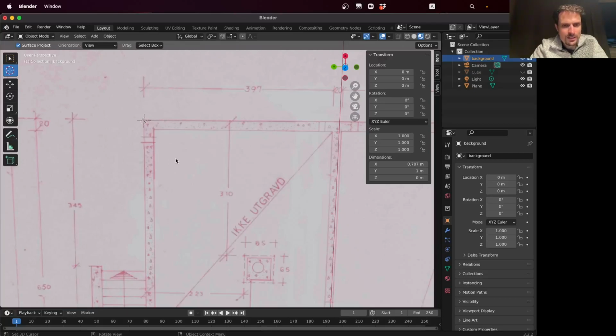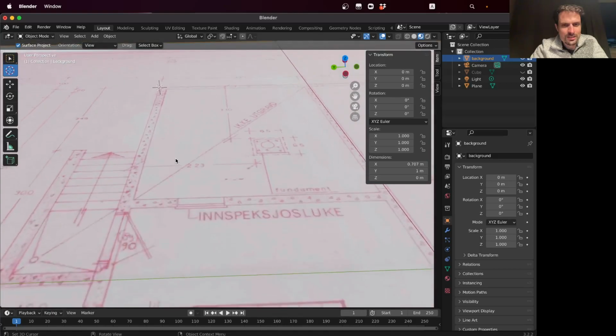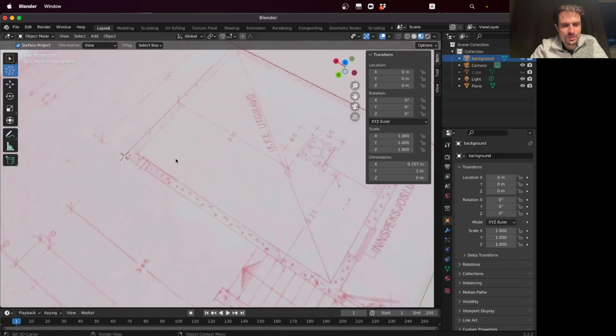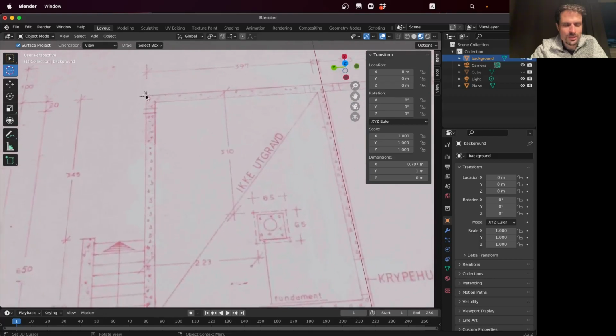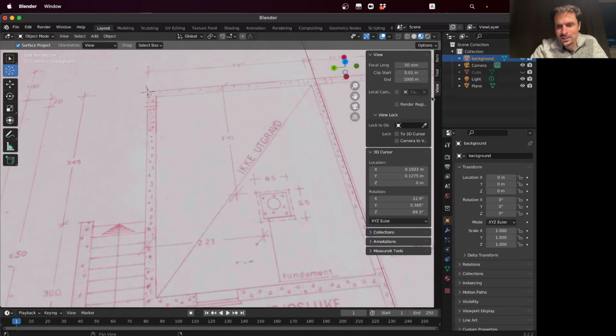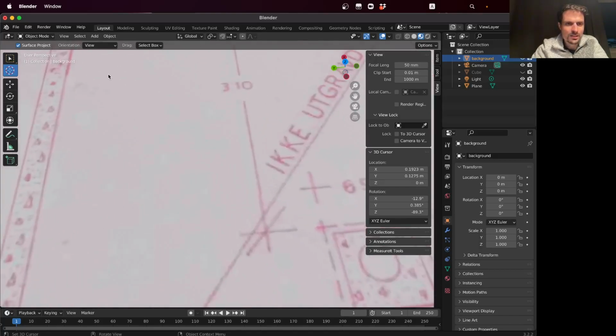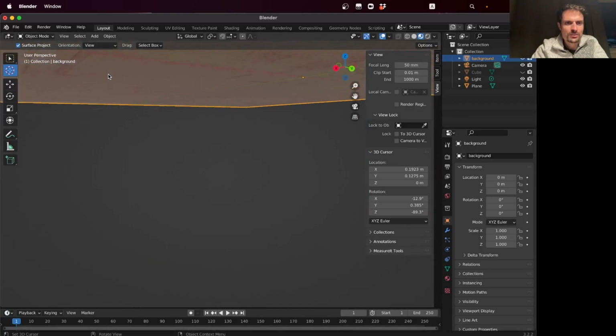One could think that since our position is not perpendicular to the horizontal plane, then perhaps this cursor is not in the horizontal plane, but we can select here in view, 3D cursor, and we see that it is actually on the horizontal plane, right? And we can double check it just by looking from the side.